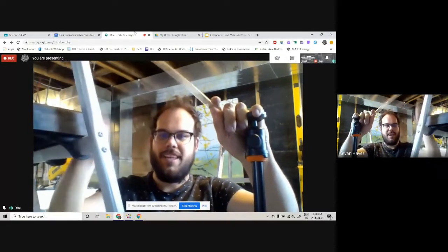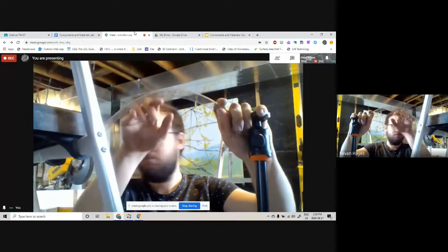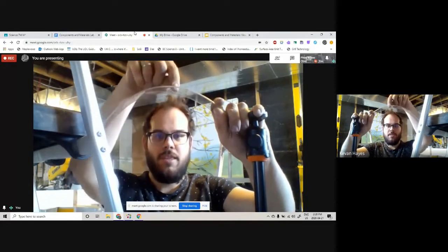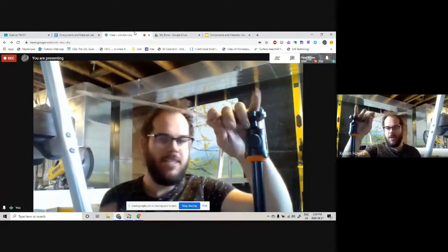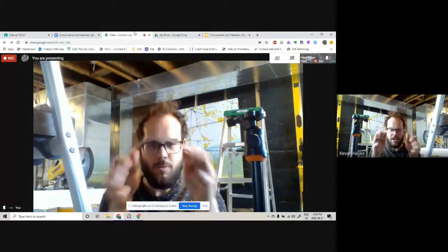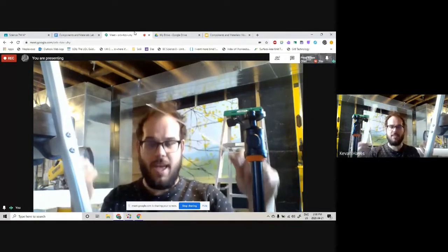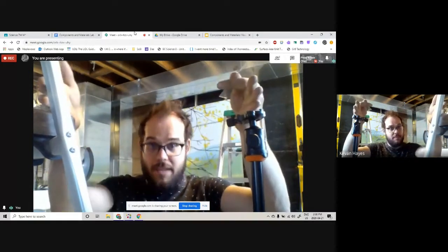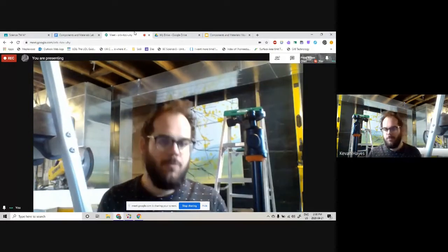But notice there, when I push on this, if the supports are able to move away, then this just flattens out and it fails. So this works so long as this is like one nice piece that can transmit forces all the way along it to both ends, and as long as the two ends are well supported. If they're not well supported, then the arch fails.